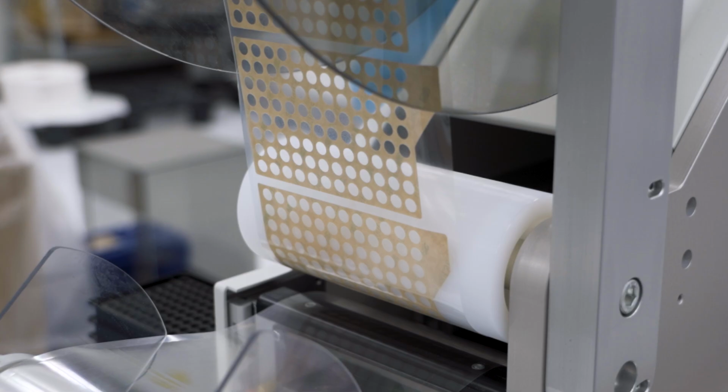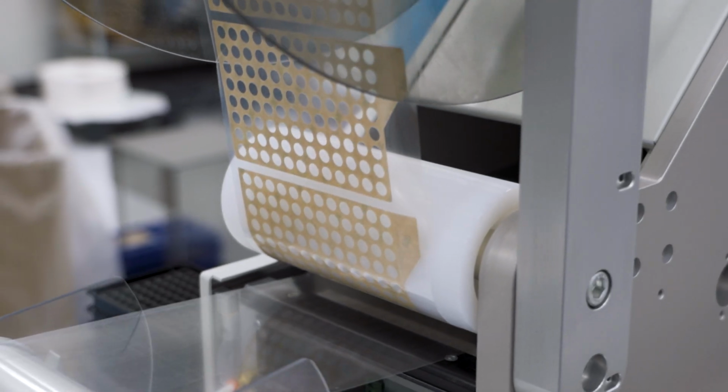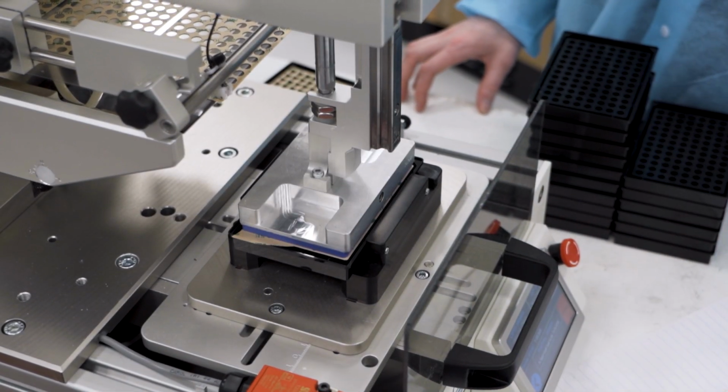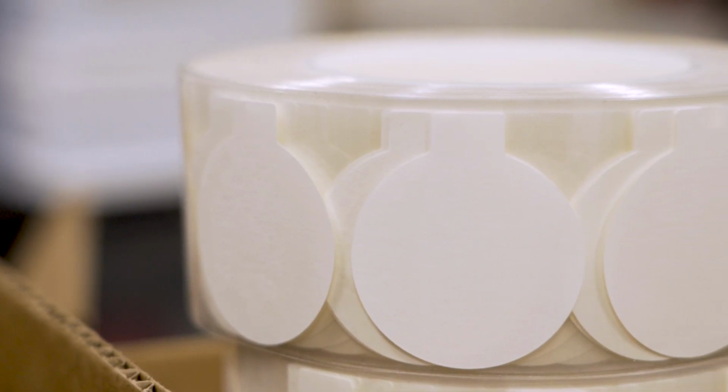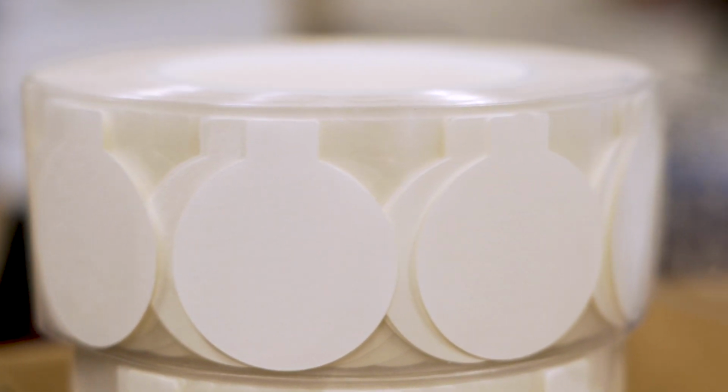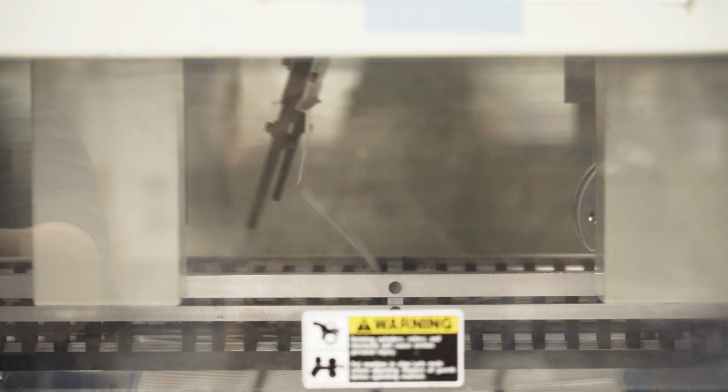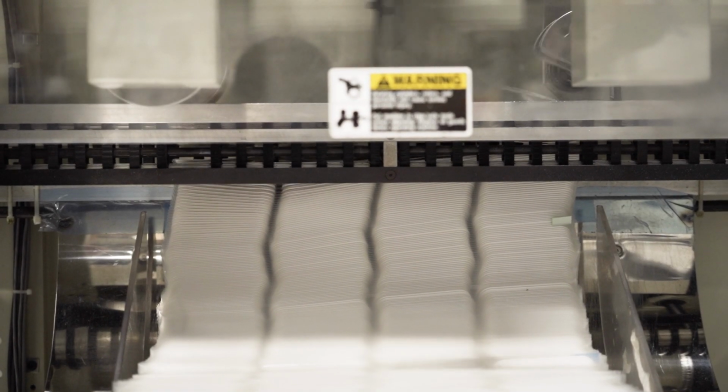To fix adhesive liner issues, the first step is to determine the desired release behavior. Automation will oftentimes require an easier release liner for the process to work correctly. However, most manual applications want the liner to stay on the part firmly until it is ready to be removed. Adjusting liner thickness can also improve part stability. In some cases, adding design features like tabs or folded liners can enhance usability, particularly in automated settings.